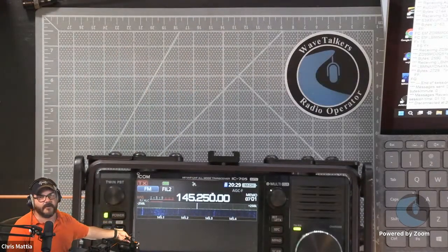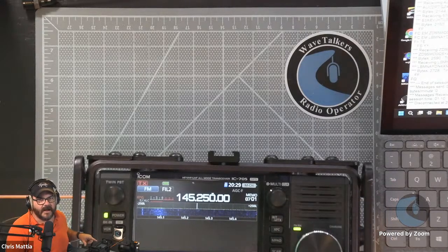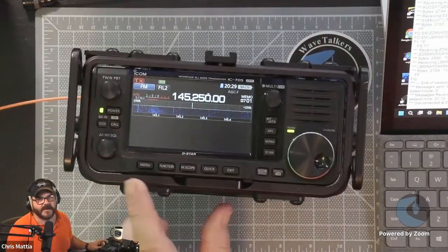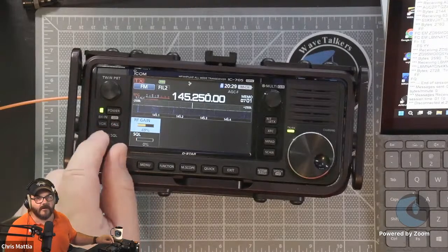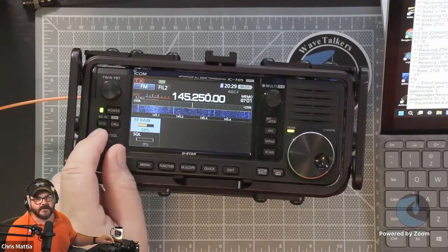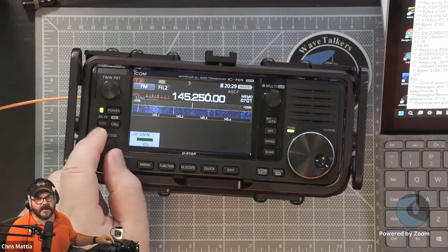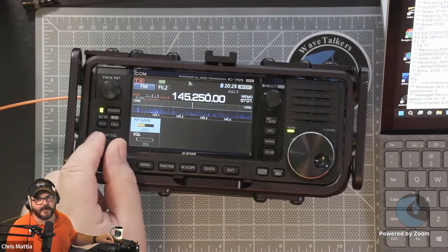And oftentimes, if you put the ferrites on, as you keep snapping ones on, you'll see the signal get a little bit cleaner each time. One of the ways that I do that is I'll press the button here, go into the RF gain, and turn that RF gain up quite a bit, so you're seeing a little more, until you get to the point where you're seeing quite a bit of noise. Turn it down a little bit, so that your noise kind of disappears a little bit.